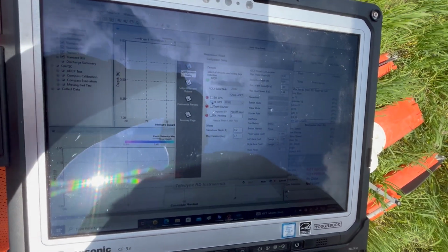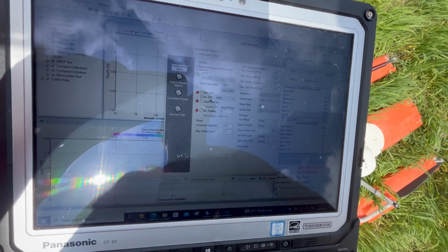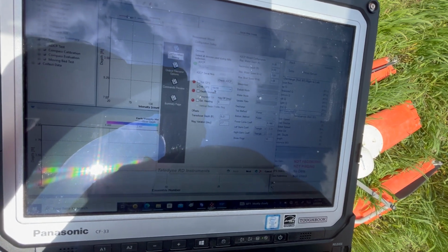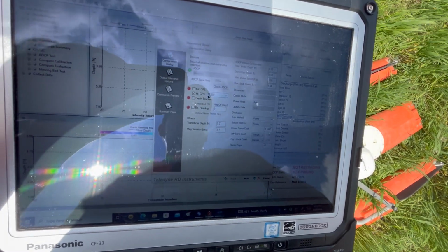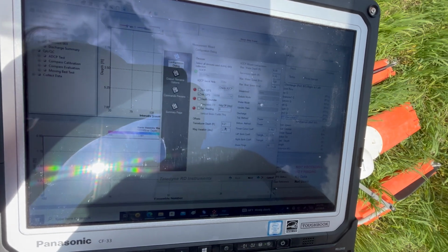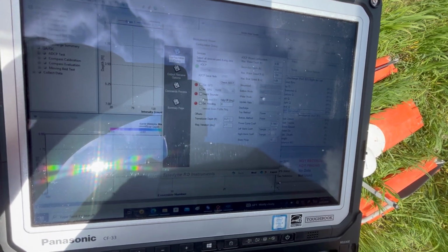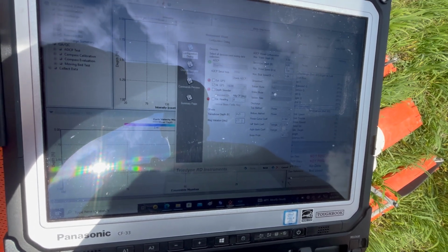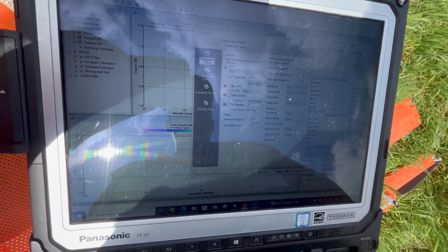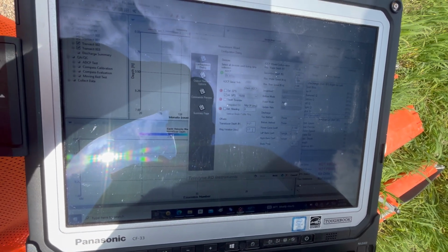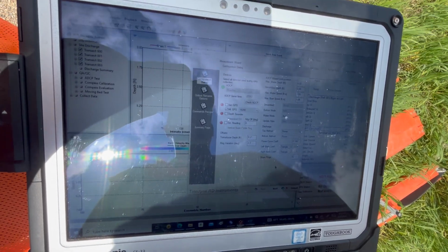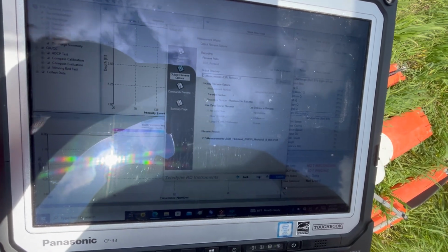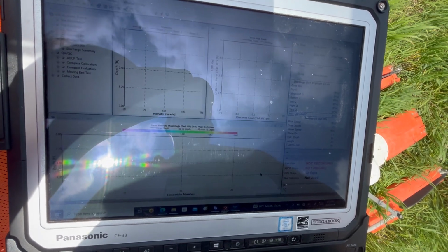We have the internal GPS. Even though it looks like it's an external GPS, it's still considered an internal. We always want this at 19,200. Our transducer depth for this, we've measured at 0.21. We have our magnetic variation declination in here at 2.7 that we got from an app. All the other settings were what the River is set at. So then we can go on from there, and this site's all set up.